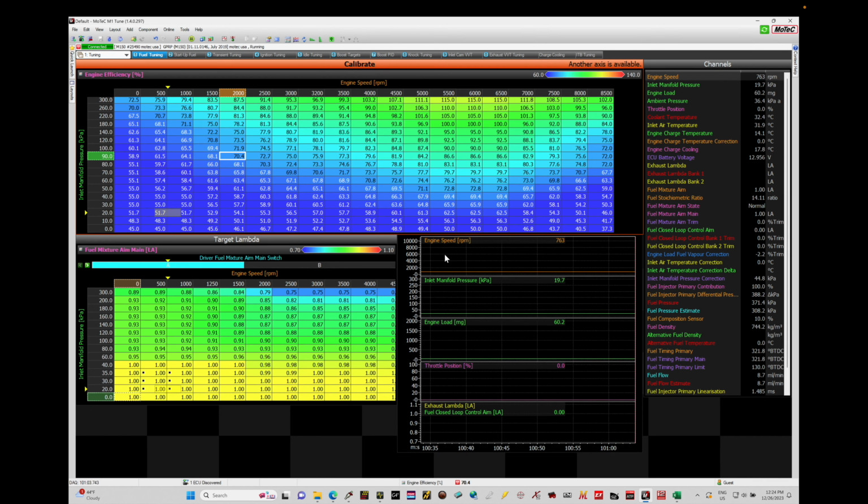Now, when we're programming and setting up our dwell time, if we have a coil that's supplied in the drop-down list we're going to be taking a look at here in this tutorial from Motec, we don't really need to do a whole lot of setup and configuration. If you have a coil that's not listed in that drop-down menu, we do have things we need to populate and understand what the coil dwell means, and then put in values for the coil dwell that make sense so we don't have too little spark energy or overheat and saturate the coil and damage it.